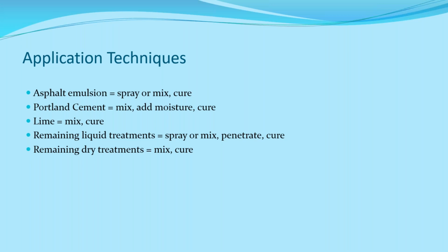The remaining liquid treatments are generally sprayed or mixed. The salts, a lot of times you can spray on the roadway and let it penetrate the roadway. And like I said, it'll penetrate down as deep as the moisture. One caution I would give you with salts is that if you have high air temperatures and low humidities,